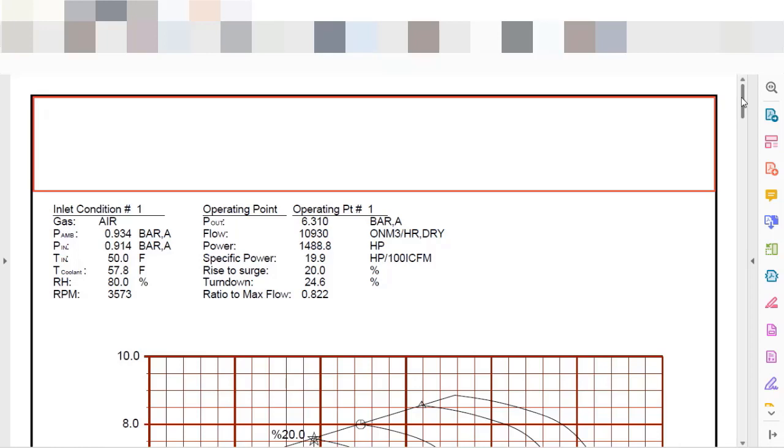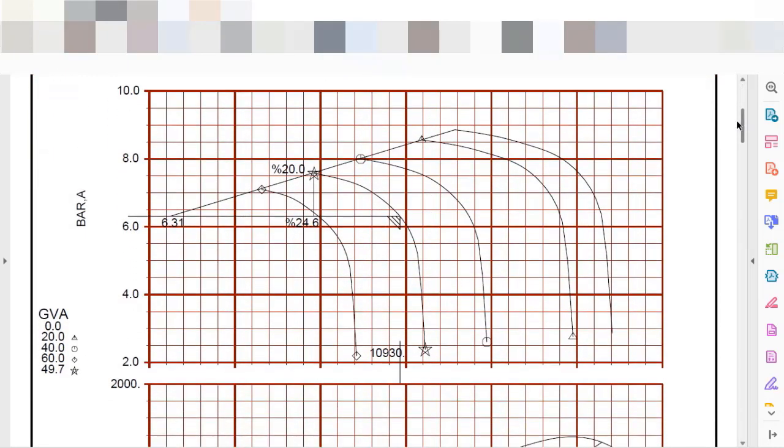And here, similar to a centrifugal pump, we have the compressor curve. So I have the surge curve here, where I cannot operate above this range because I will be in surge conditions. And for each line here, I have a condition of opening of a guide vane. The guide vane is responsible for adding more or less flow to my equipment. The guide vane will add a pressure drop to the equipment so that I can choose the range of operation.